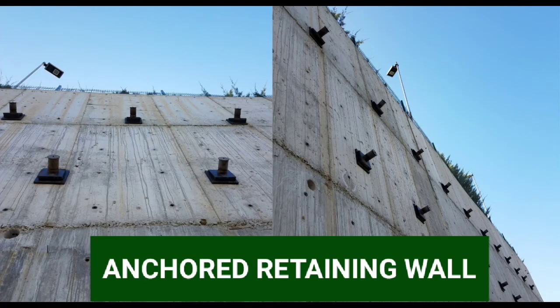This one is the anchor retaining wall. This type of retaining wall is employed when the space is limited or thin retaining wall is required. Second point, anchor retaining wall is suitable for loose soil or rocks. Third point, considerably high retaining wall can be constructed using this type of retaining wall structure system. Fourth point, cable rods or wires are driven deep sideways into the earth. Then the ends are filled with concrete to provide anchor. Last one, anchors act against overturning and sliding pressures. This is the anchor retaining wall.